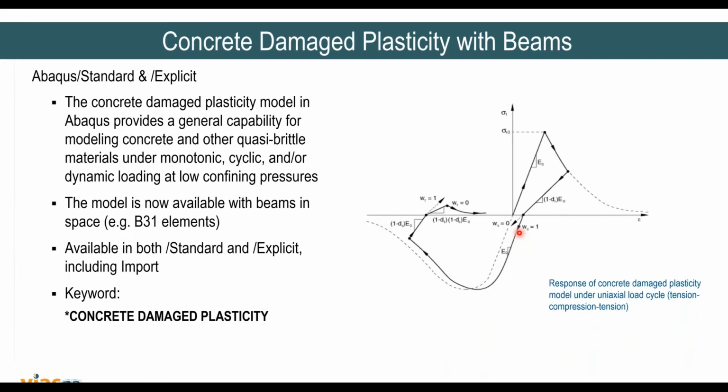Concrete, and the next enhancement that I'm going to talk about is the concrete damage plasticity. You must be aware that concrete damage plasticity has been there in Abaqus for quite some time, and it provides the general capability for modeling concrete and other quasi-brittle materials for monotonic, cyclic, and dynamic loading. But this material model was not available for the beam element.